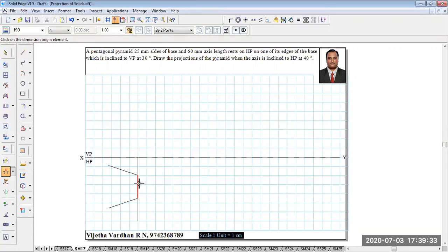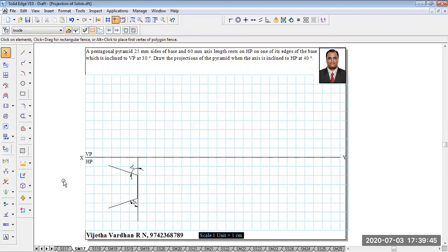That is nothing but here you are supposed to measure 72 degree on both sides from both the respective corners. And once you have drawn the 72 degree, please confirm that you have drawn 72 degree, because there may be a chance that you create it as 68 degree. So please make sure the exterior angle is supposed to be 72, not 68. There is a general tendency that some of the students may end up with 68 degree instead of 72 degree. So please be careful over here.